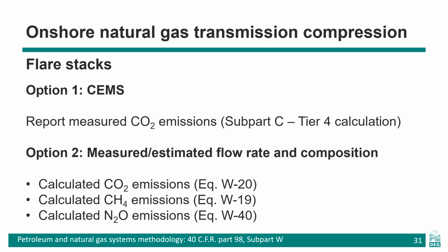Flow rate and gas composition data should be taken from the measured flow rate and composition data if available. If no instruments are installed, it is acceptable to use best available data to calculate the flow rate and composition. Make sure that emissions being included within this section are not double counted from other emission sources where those emissions have been routed to the flare.